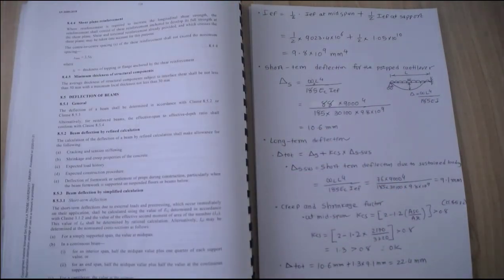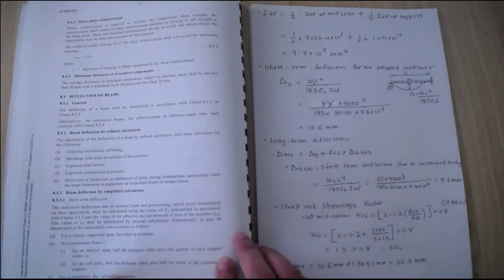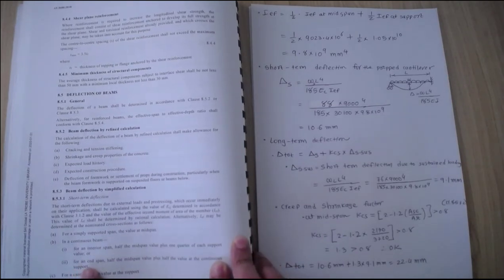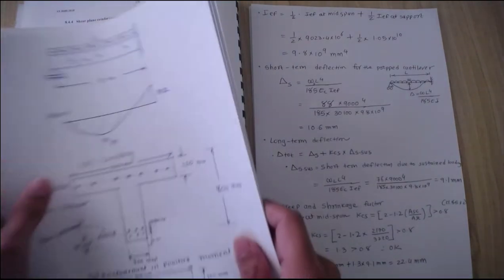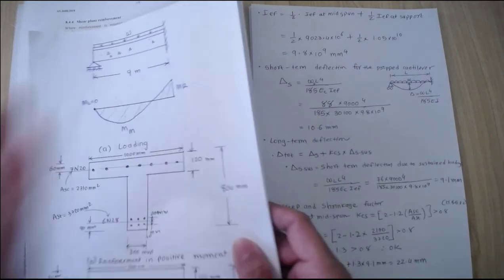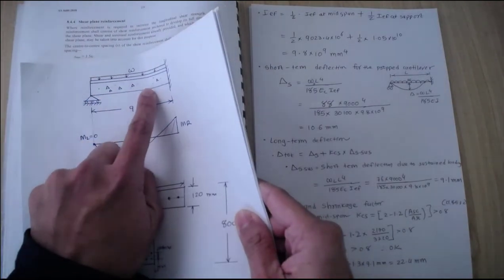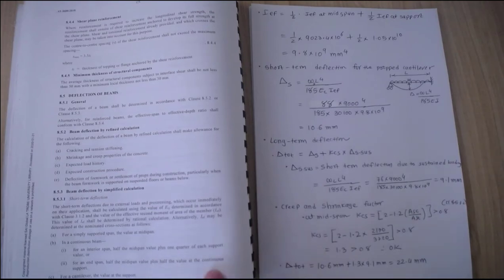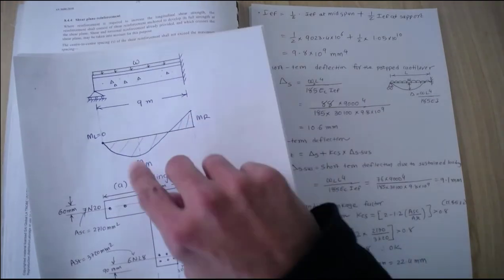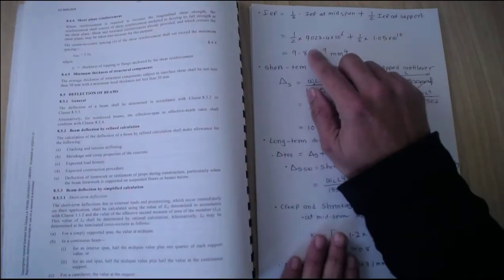After calculating I effective at the mid span and I effective at the supports, we are using clause 8.5.3.1, where it says that for a continuous beam, we are taking this one as a continuous beam. It's not continuous, but it can be classified as a continuous beam. So in that continuous beam, this is an end span, if you are looking from this side or this side. Half at the mid span plus half at the support. That is the I effective for this beam. So I effective here plus I effective here, half value will give me the I effective value for that beam.